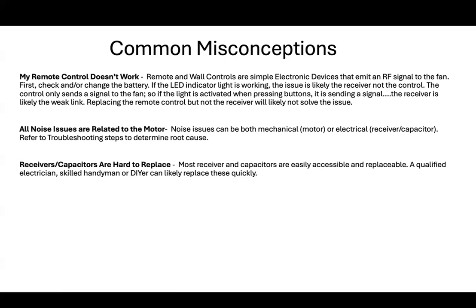Common misconceptions. Here are some common misconceptions about ceiling fans you may run into. Number 1, my remote is not working. Remote and wall controls are simple electronic devices that emit a radio frequency signal to the fan. First, check and/or change the battery.